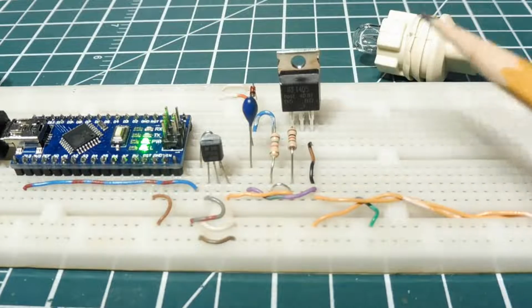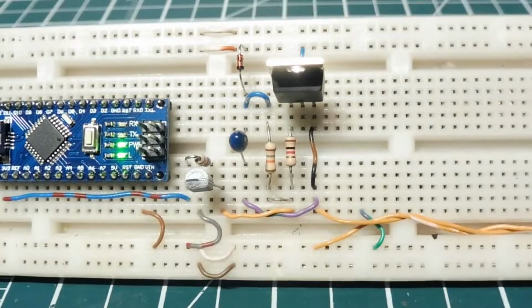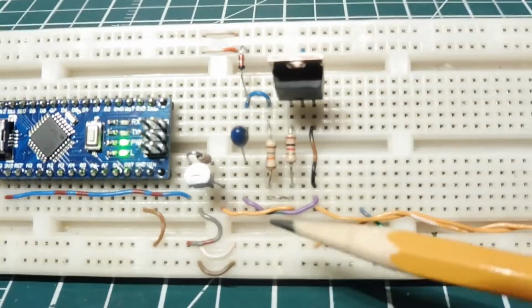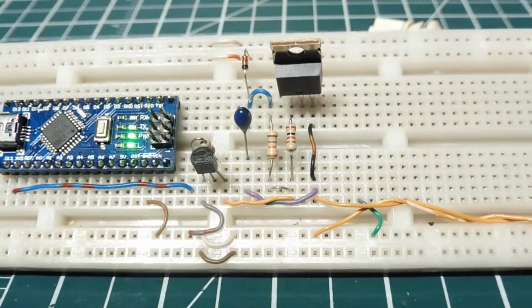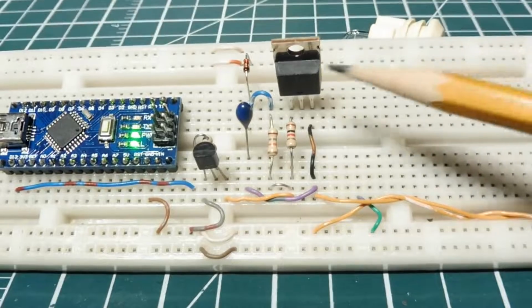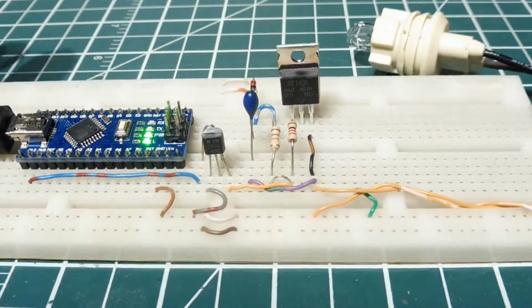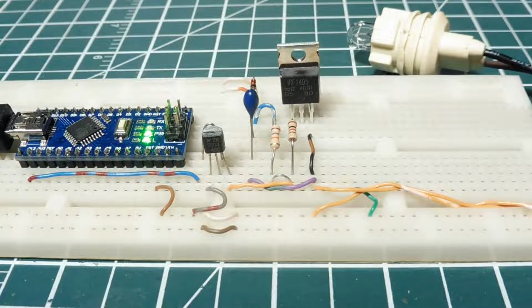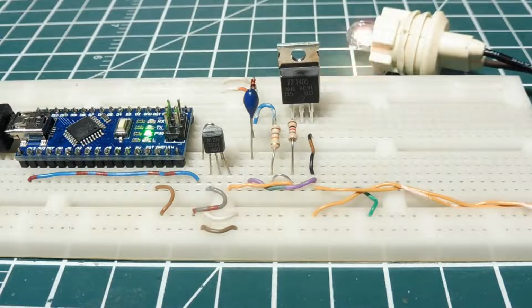Now the circuitry has a low parts count. You can have a look at it. There are two resistors, a capacitor and a diode, and then the N-channel MOSFET. That's all we need for our bootstrap circuitry, and that's going to give us 24 volts to drive the gate on our MOSFET. So I can activate the program to blink the bulb. There she's turning the load on and off through the Arduino Nano.